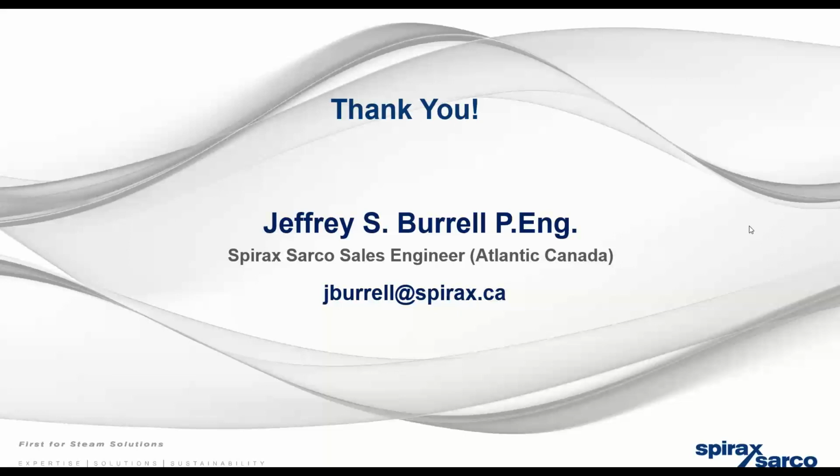One way we've seen is we've supplied what we call inline condensate mixers. Now they don't eliminate water hammer, they reduce water hammer to an extent. Unfortunately, it depends on how much high pressure condensate you're getting as well. So there's a few things in there that need to be looked into, and it can't be a lot either. The other way was also to do a flash tank, knock the high pressure condensate down to lower pressure, and then mix them at similar pressures that way too.